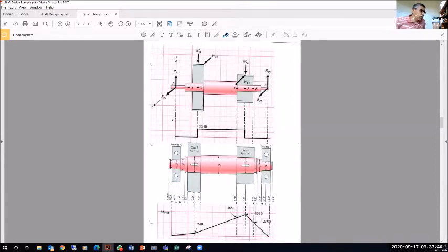Now here, this is a groove. Here, this is a groove. I have another groove and a fourth groove here. You see the keyway, because it said that the torque is being transmitted by a key. So this is also going to be a critical location at the end of the key. So I may want to look at this location here.